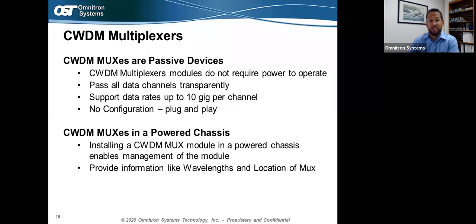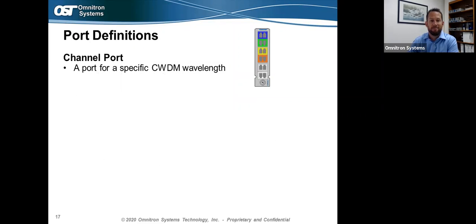You can also insert a CWDM multiplexer into a powered chassis, and what this does is give you some management capabilities. So you can easily monitor the wavelengths being used or the locations that these multiplexers are residing in.